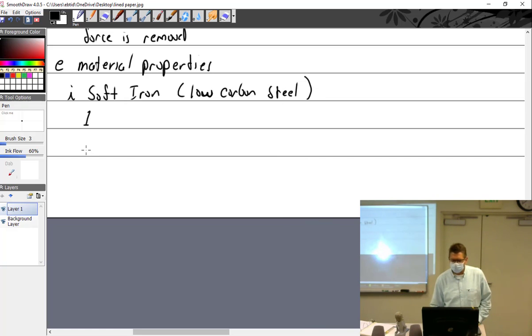Okay, so back to what I was saying. Why would you want to make something soft? Well, I said because you want it to be a little more bendable. The harder something becomes, the more brittle it becomes. Yes, it's very hard. Like a crankshaft, you want those journals that it's going around inside the bearings to be hard because you don't want it to wear, right? But you want some parts, other things, to be bendable.